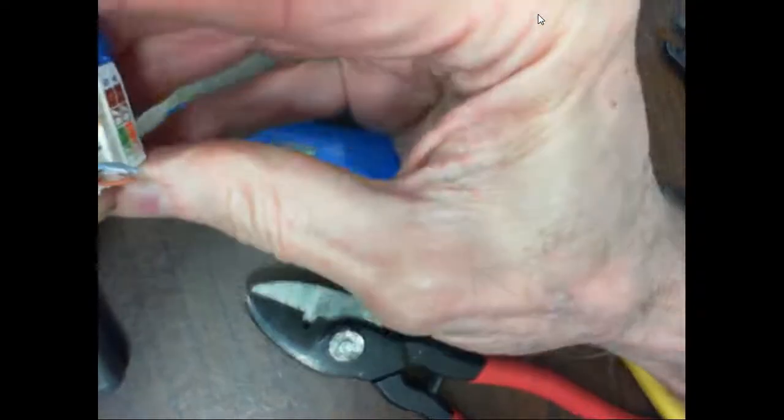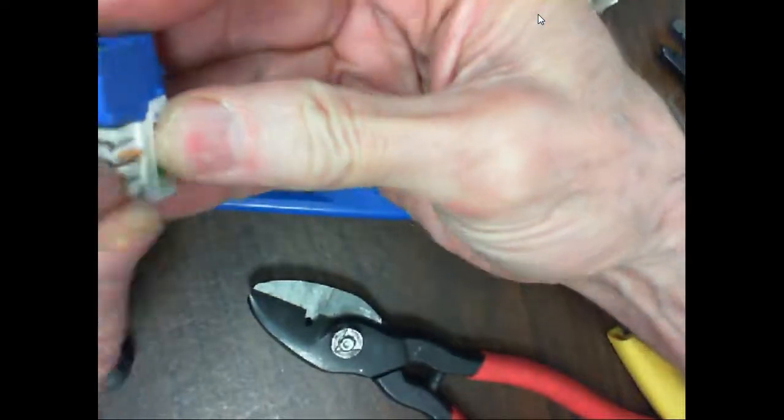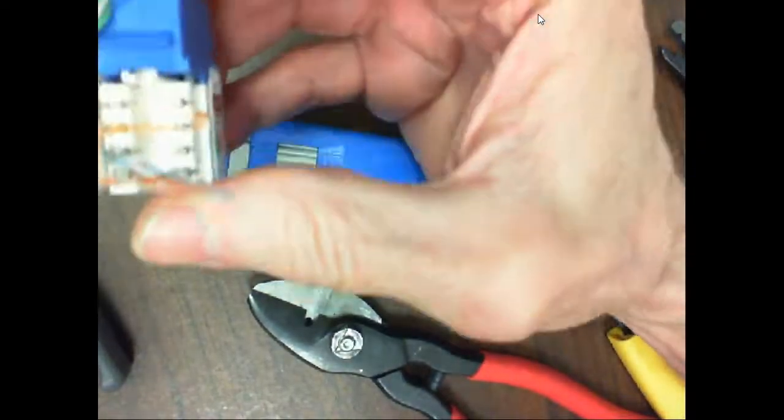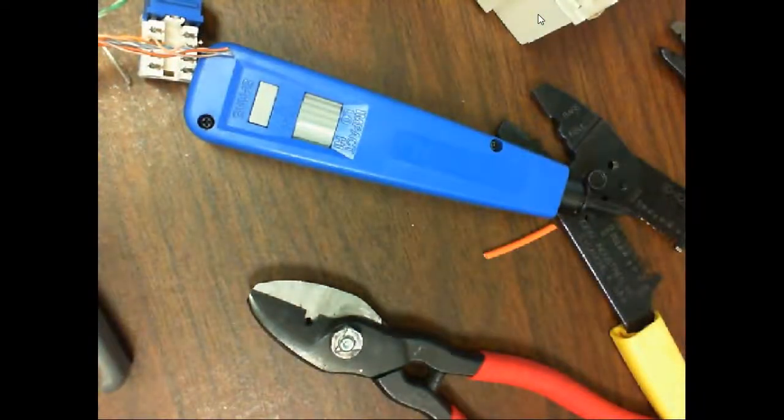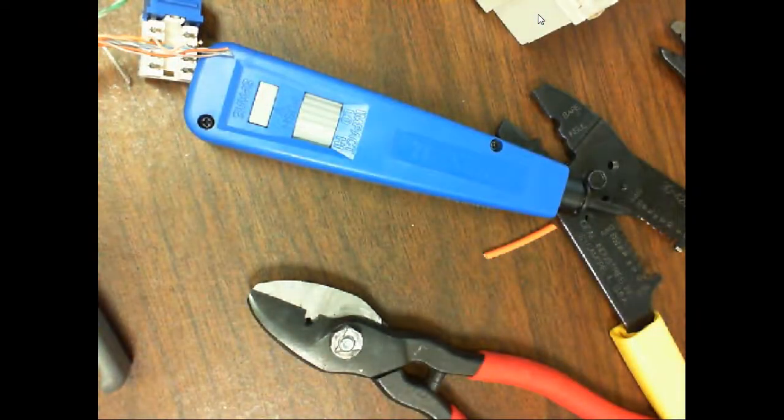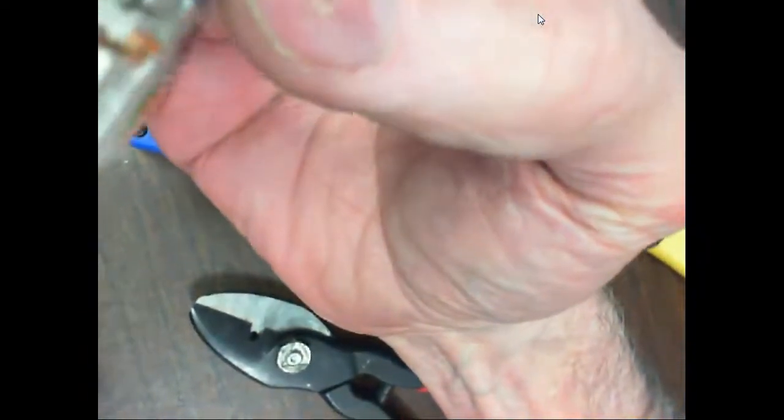and then we'll push it, and then what would it automatically do? It didn't cut mine off, so I'm going to have to do it more than that. And then it'll do what? It'll cut off the end for us. And what it does is it pushes it down there, and you see how it got the name as a punch down block. So I guarantee you, if we took this cover and pulled these gray boxes out on the side, these little punch down, these 110 punch down blocks would be in